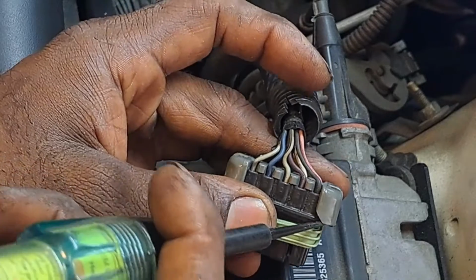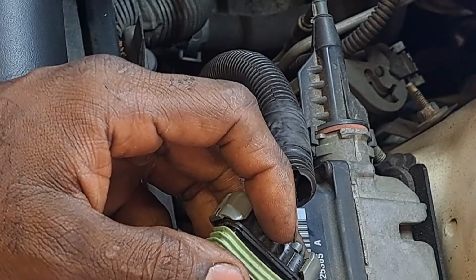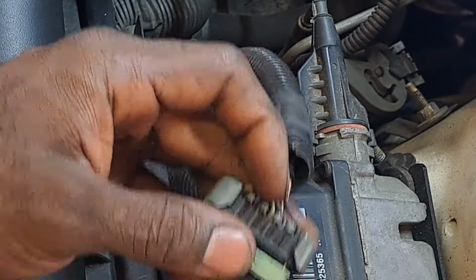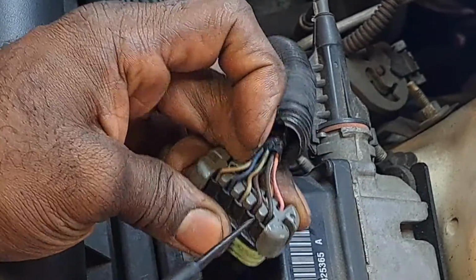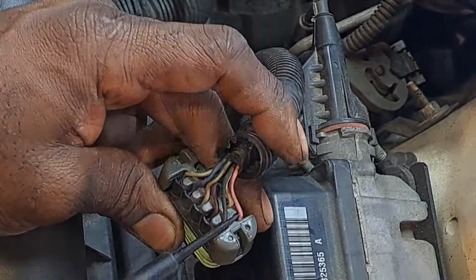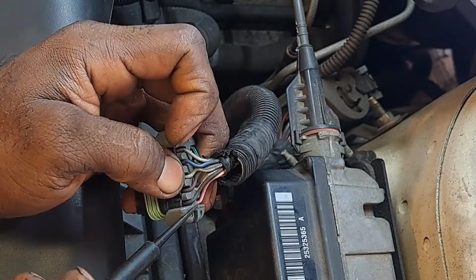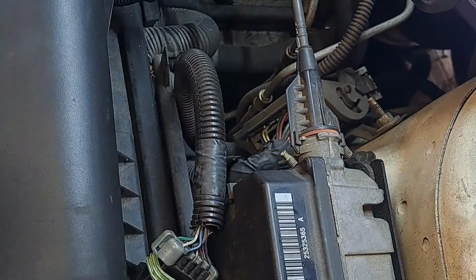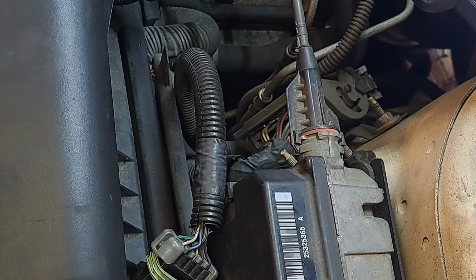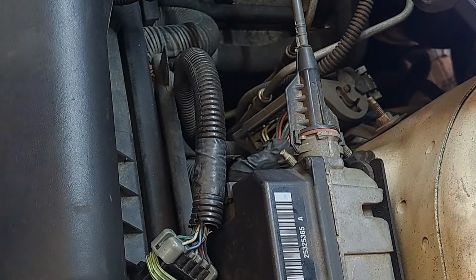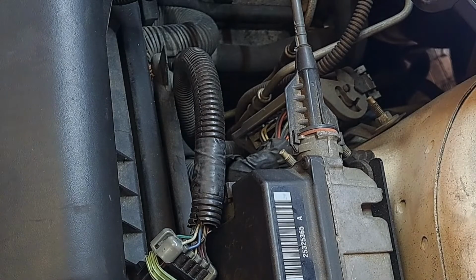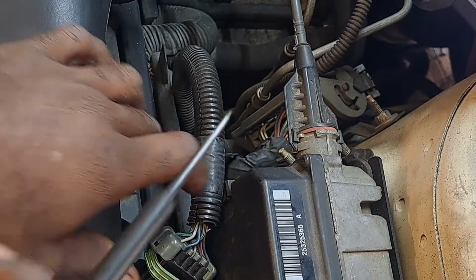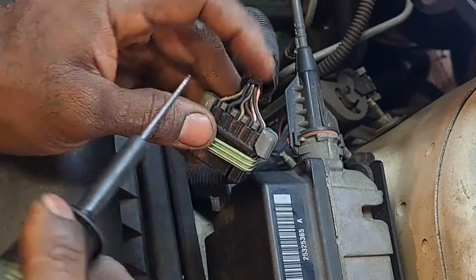The next thing we're going to check is the power, which is our ignition, the pink wire. That's F, next door to it. Testing this power source, I'm going to hook up the alligator clamp on a ground source. So instead of positive, looking for a negative, we're going to go to negative to search for a positive.